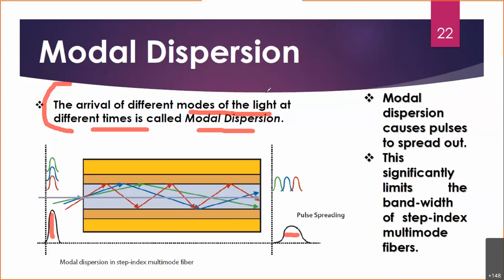But remember one thing, it is a continuous development, one can say. Earlier we had the concept of the step index fiber, but then we identified a problem with this optical fiber: we are not getting our output perfect compared to the input. So they thought about where exactly the problem is, and they came up with an idea about the core refractive index. Right now in the step index optical fiber, the core has uniform refractive index throughout, and suddenly it changes at the cladding. That is why we say the refractive index changes in the form of a step.